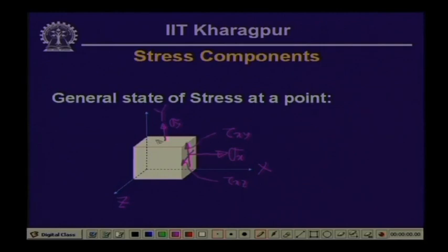In the positive direction of x on the y plane, we have the shearing stress, which is designated as tau y plane x direction, tau yx, and on the y plane in the z direction, we have the stress which we designate as tau yz.